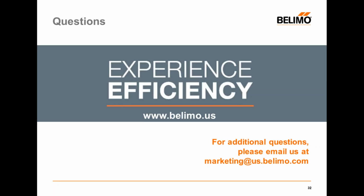Oh, that's a very good question. In some cases, building operators with larger buildings do prefer this, what we might call single seat control. So you can control and monitor both your HVAC and your fire alarm through one location. This is especially relevant if you have a non-dedicated system where you're using your HVAC for smoke control as well. One thing to keep in mind, if this is going to be done, the building automation system's front end has to be UL listed for smoke and fire alarm control.